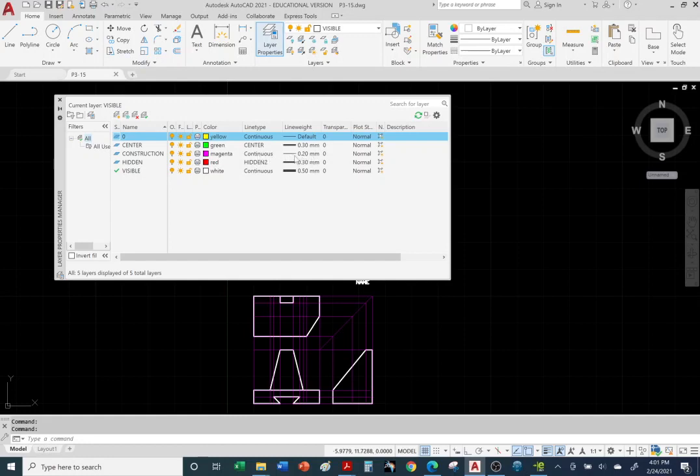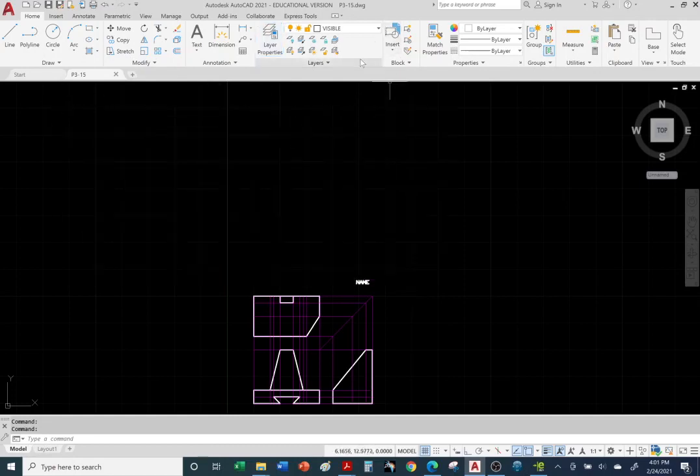You can go with no thickness, or I chose 20, but I should just leave it at default at 0, but you'll still be able to see them. I chose continuous solid lines, and that's what you see here in magenta. These are guidelines. Let me go ahead and turn off layer properties. Again, you'll be creating your own from scratch later on.